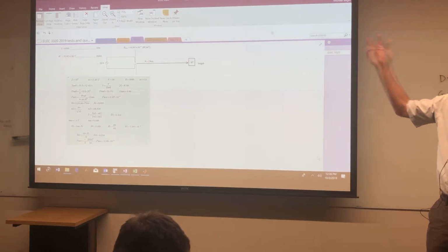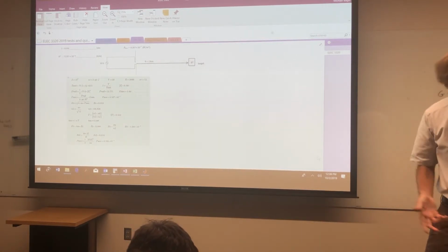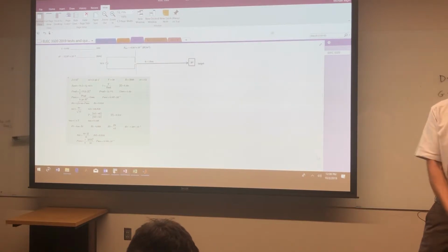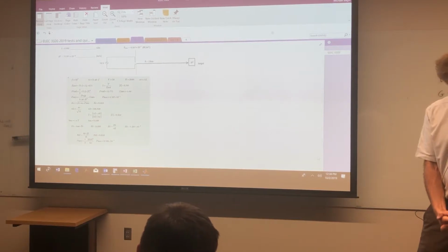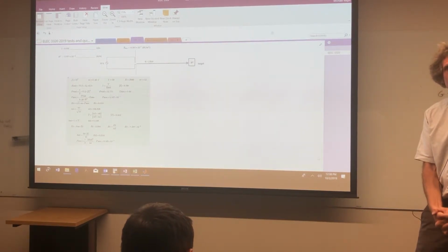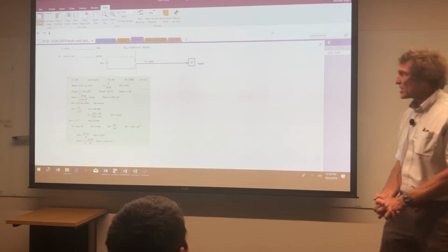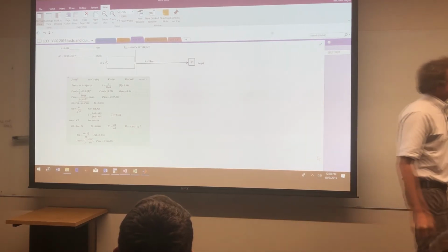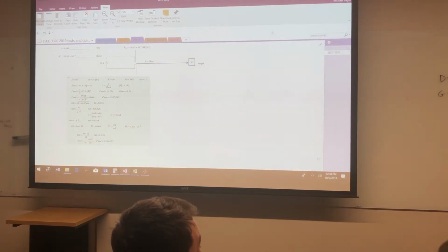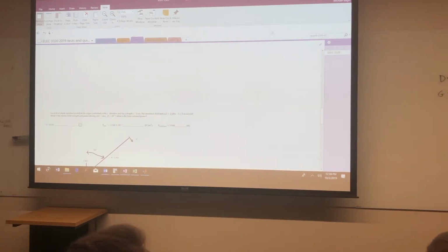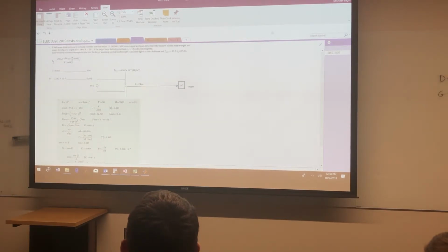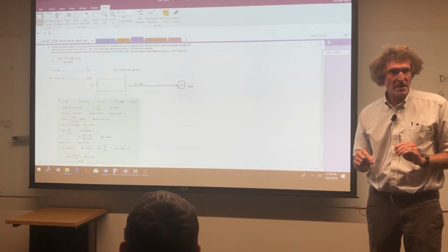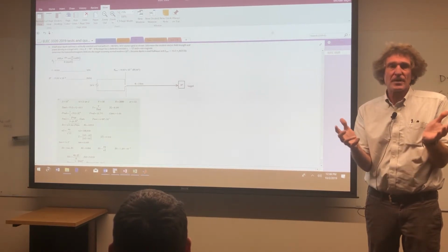Now, this one's straightforward. Just listen to me now with the method. You have the antenna impedance. You need the antenna current. You divide the voltage that's driving it by the antenna impedance to get the current, right? Now, once you have the current, please listen. This is important. Once you have the current, you can do one of 2 things. I gave you the E field up here, the equation for the E field, right? Y'all see that equation for the E field right there? You can just plug that in and get the E field, right? I gave that to you for that reason.